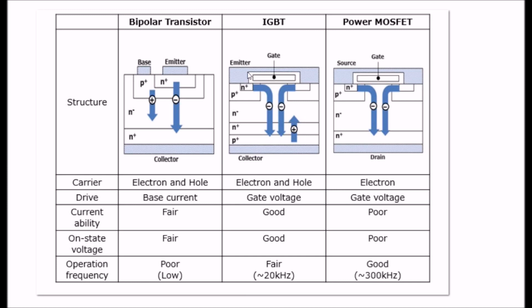Here with an IGBT, and I'll address those on different videos, you notice that the emitter, which goes to the negative side or ground, most of the current flow is from negative to the positive collector again. Isn't that interesting? Go to a power MOSFET. N-channel, its source is negative, and all of the current is negative to positive. The drain is positive.